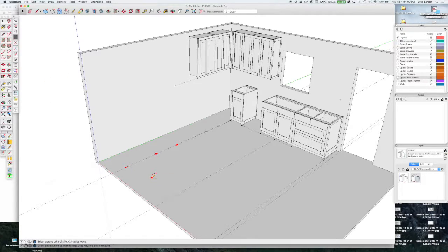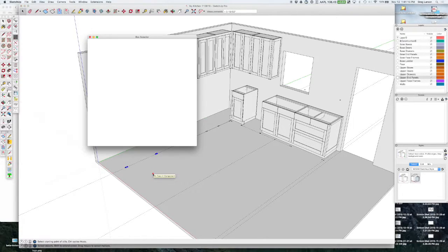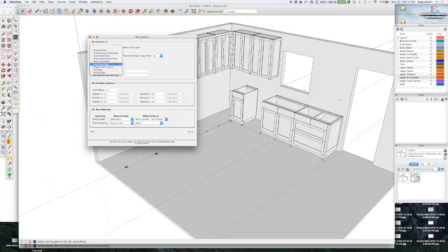So we are going to now draw our cabinet. So I'm going to hit the Command key on the Mac, or the End key also works, and select a box type. So here's our new divided base. Now you have the option, there's some divided base options here. We have the option to set a shelf offset from the rail. I'm going to do 5/8 of an inch, and I'll show you what that does for us. That's the offset from the bottom of the shelf to the bottom of the rail. So I'm going to have it stick up 5/8 of an inch, which is going to make the shelf peek out a little bit. I like to use that as a doorstop, and I'll show you.